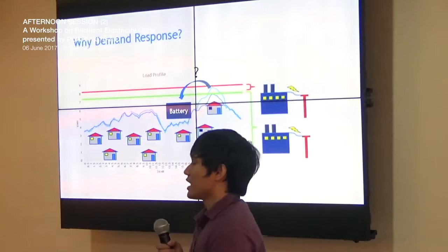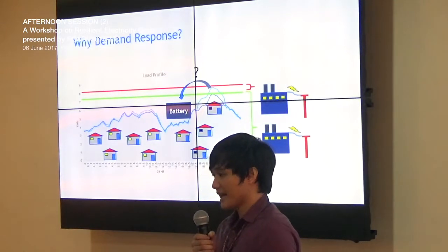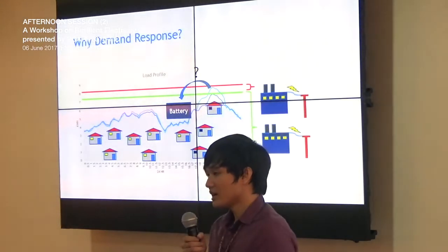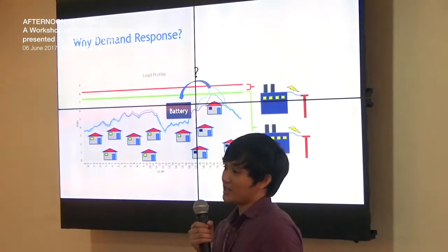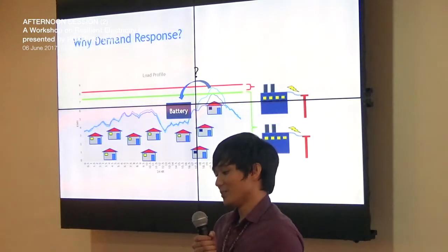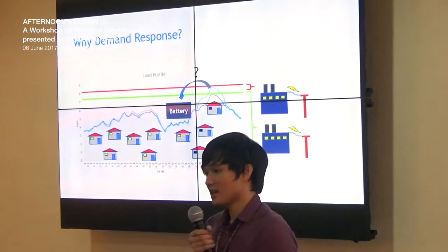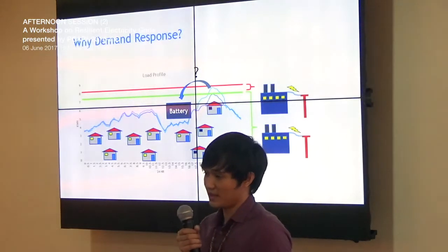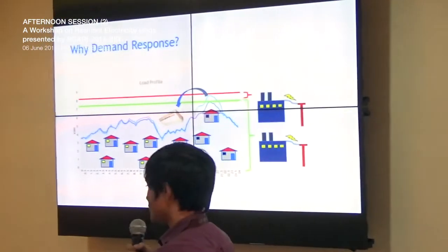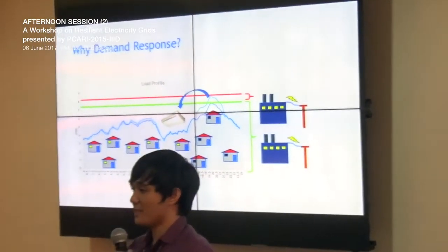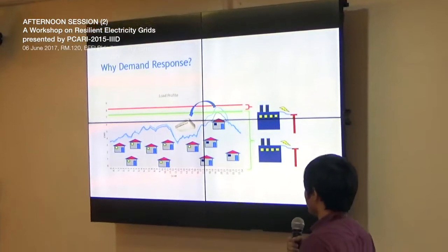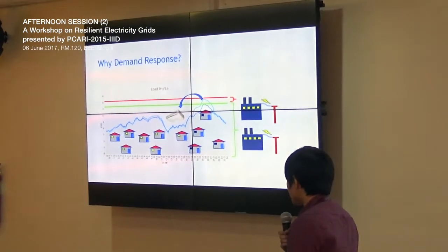That just means that if I put in effort now, that effort would be sustained over a long period of time. The transient response for your consumption would be relevant for up to 15 to 30 minutes for typical buildings or rooms. So we could use HVACs to implement demand-side management techniques, or in this specific sense, what you call demand response.